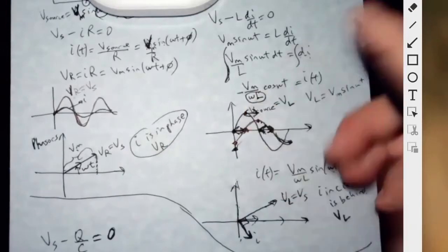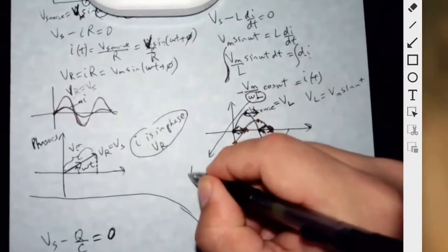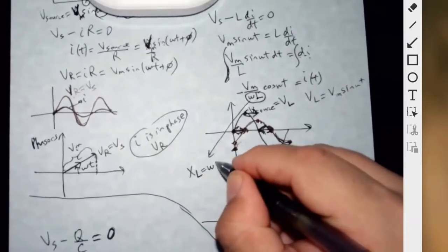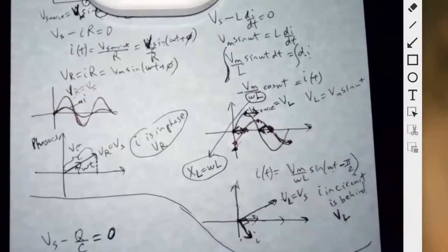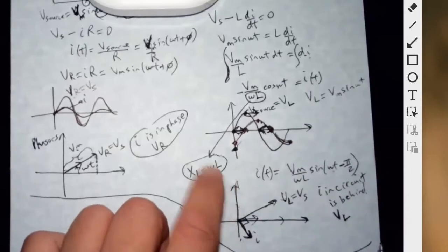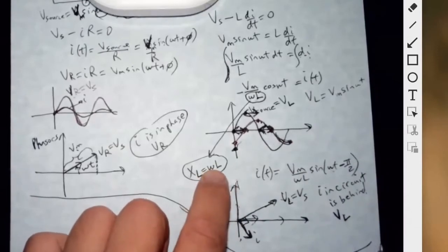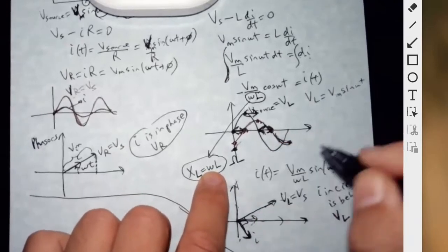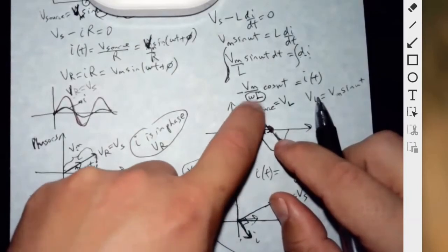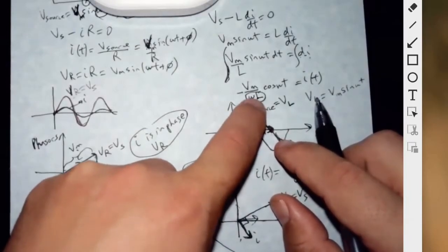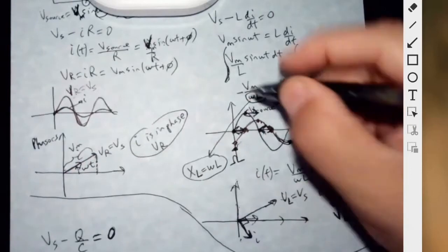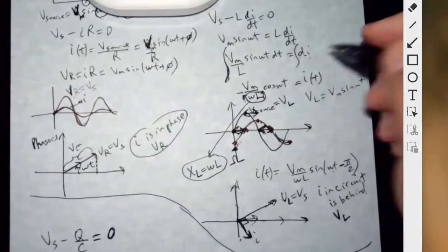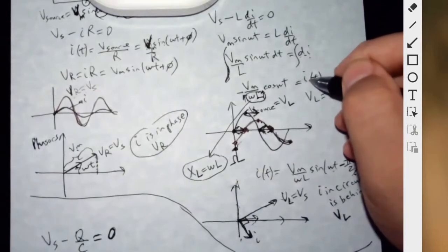And therefore kills the current by that amount. So this is called inductive reactance, XL, and it's omega L. If we analyze the units of this, it should come out in units of ohms. Because it's a measure of how much an inductor resists current in an AC circuit, you see. The bigger the omega is, the bigger the inductance is, the smaller the current is, you see.